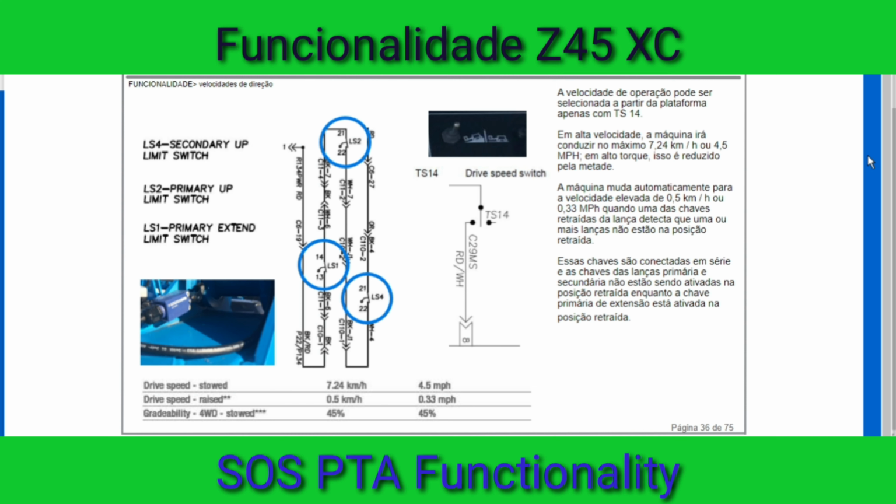The machine automatically shifts to elevated speed, 0.5 km per hour or 0.3 mile per hour, when one of the boom stowed switches detect that one or more booms are not in stowed position. These switches are connected in series and the primary and secondary boom switch are not activated in stowed position, while the primary extend switch is activated in stowed position.